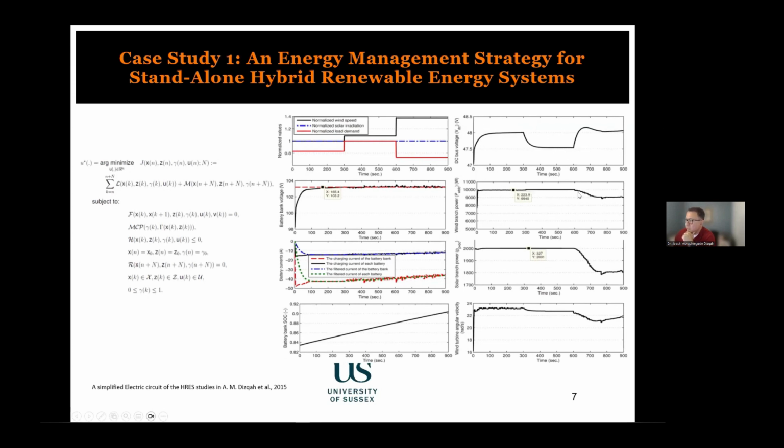Also, by doing the curtailment of the solar and the wind, the charging of the battery is with a slightly increasing current, but at constant voltage. It helps to charge a battery to a larger SOC without damaging the battery. And this was the main purpose of this algorithm.